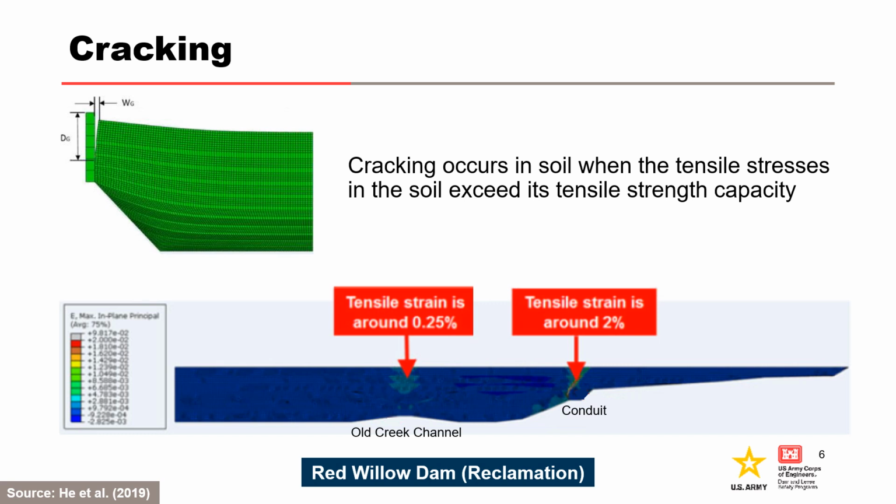When an embankment dam is constructed, differential settlements occur across the valley, resulting from parts of the dam being higher than others, settling more as the dam is constructed. This can lead to horizontal strains and potentially cracking or low stress zones susceptible to hydraulic fracture. This is most likely to occur where the abutments are steep, where there is a step in the foundation profile, or where there is compressible soil in part of the foundation.